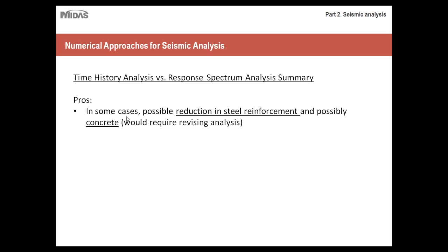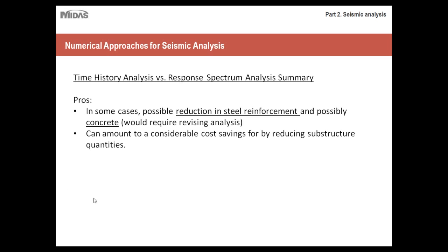So once again, that's just another way to say that with time history analysis, you can create designs that are more optimal because you have results that are more realistic and less conservative. Also, it can amount to a considerable cost savings by reducing substructure quantities.